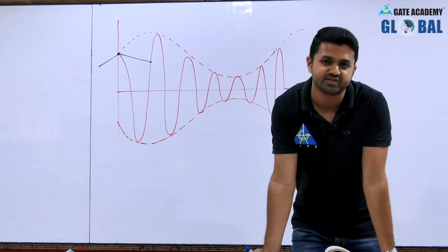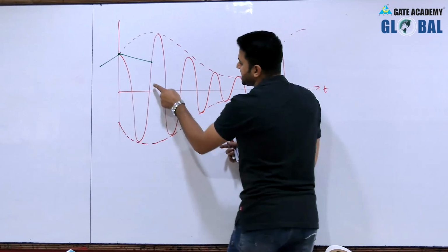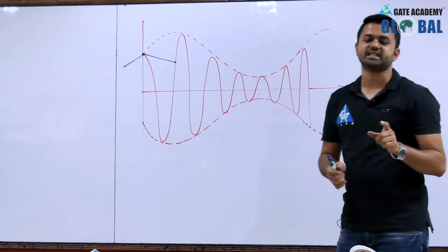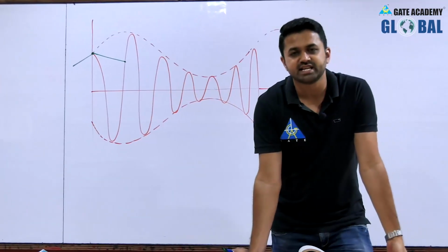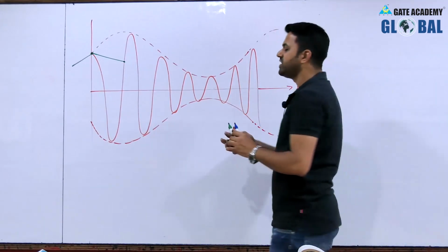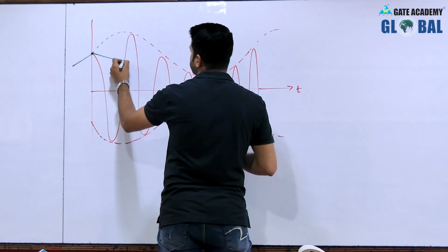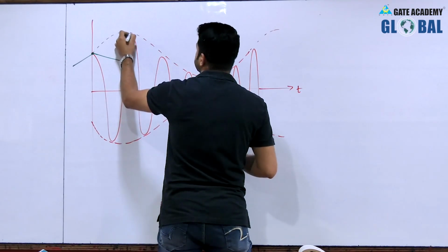the voltage at the input of this envelope detector is increasing. When the voltage is increasing, the voltage on the P side is greater than the N side, so the diode is forward biased, and the capacitor starts charging.